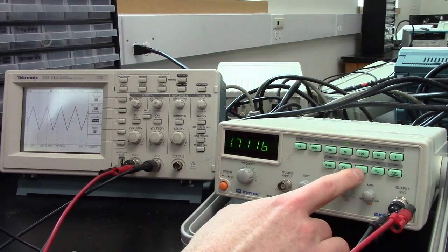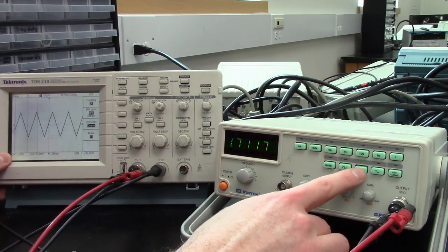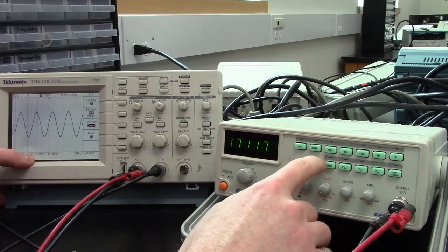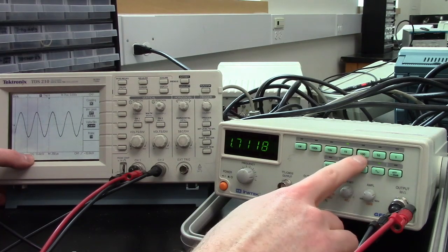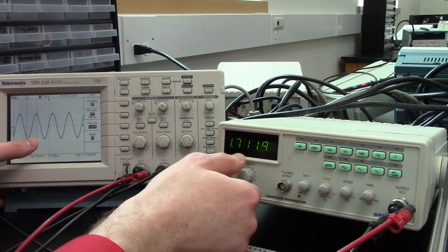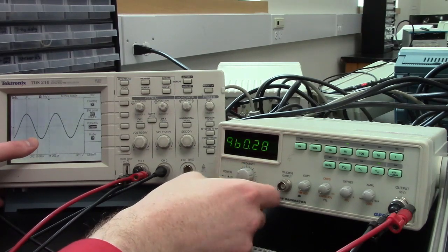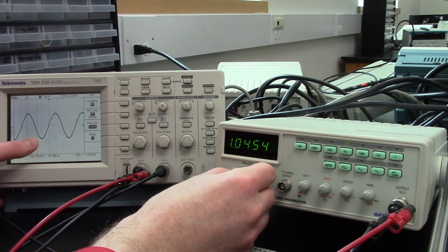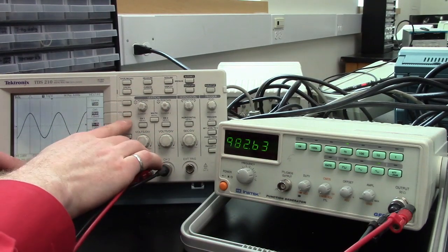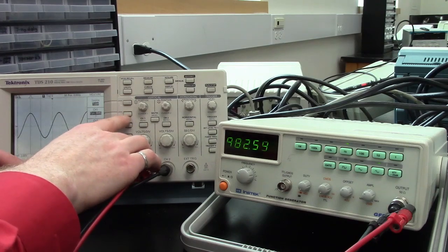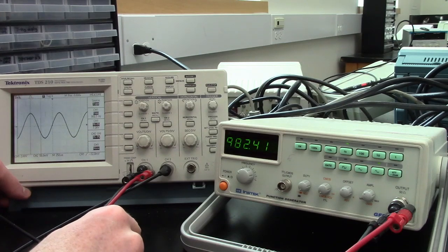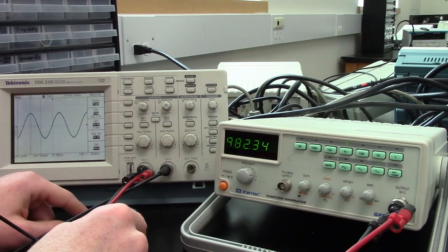So this can decide whether you have a triangle wave here with this button, square wave, sine wave, and it adjusts the frequency by the big range indicator at the top. So in the 10K range, 1K range, and then you make precise adjustments to that with this dial here. And you can read on the top what it thinks the frequency is, and also measure what the frequency is over here on the scope. So here we've got 982 hertz measured, and the scope is measuring between 982 and 984.